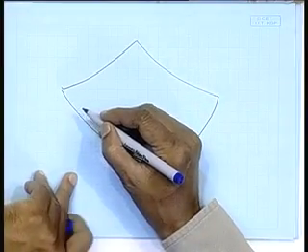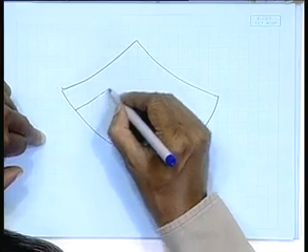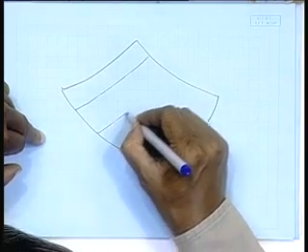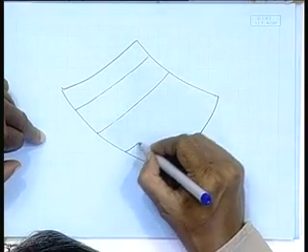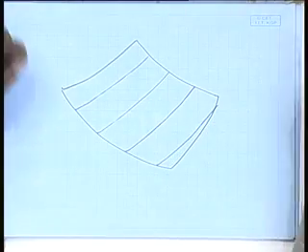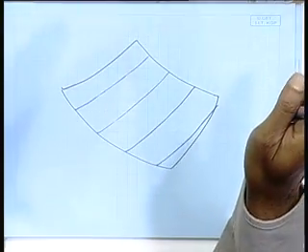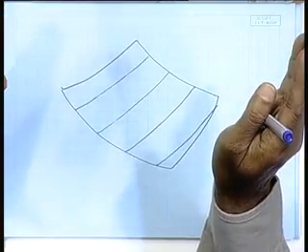Those templates are already there, as for frame bending you have done, and when you produce the blanks, you mark the frame locations. The frame locations are already marked. That marking is also automatically done in the flame cutting machine, because when you have the definition of the blank, that means the two-dimensional plate that has to be cut, that cutting is done in a numerically controlled machine.